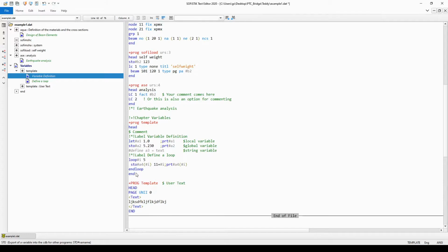However, the software doesn't know anything about a variable that was defined with the let command when the current block or module has ended. The defined values of the variables can be printed in the module with the help of the command PRT, and they will be presented in the result viewer when the module has been run.